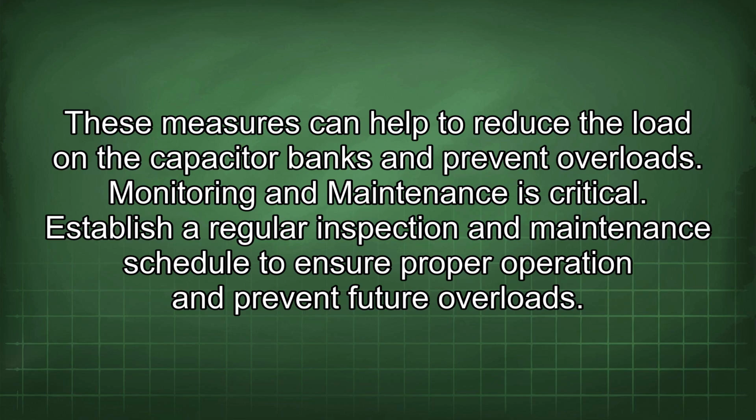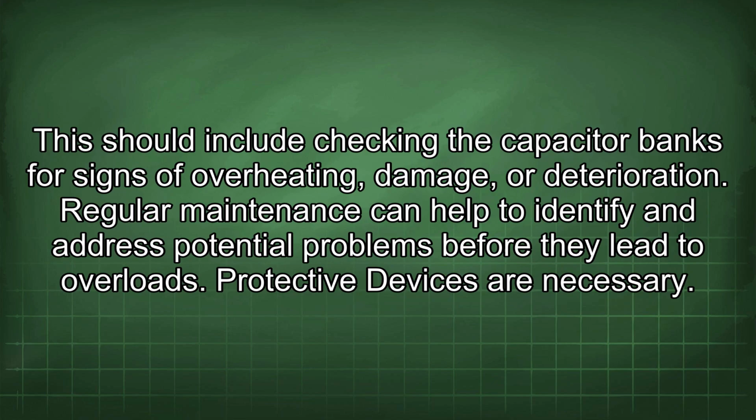Monitoring and maintenance is critical. Establish a regular inspection and maintenance schedule to ensure proper operation and prevent future overloads. This should include checking the capacitor banks for signs of overheating, damage, or deterioration. Regular maintenance can help to identify and address potential problems before they lead to overloads.